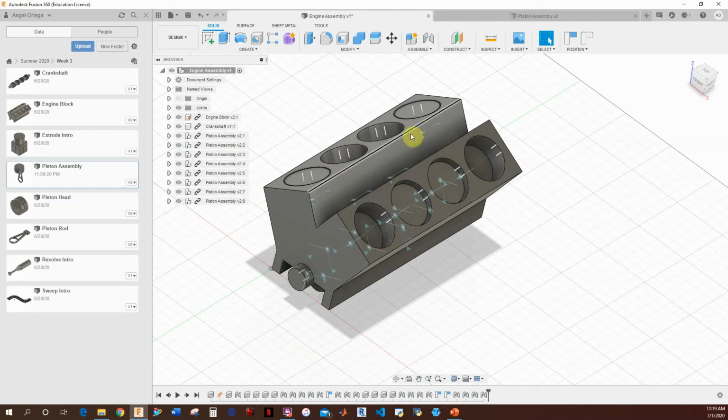So it now keeps a lot of force on the right, and then it keeps a lot of force on the left, and once you start hitting the gas and this thing's accelerating, then those forces will probably break everything in your engine bay. You'll destroy the engine mounts, and you'll probably have your engine running away from your car, which is not good.